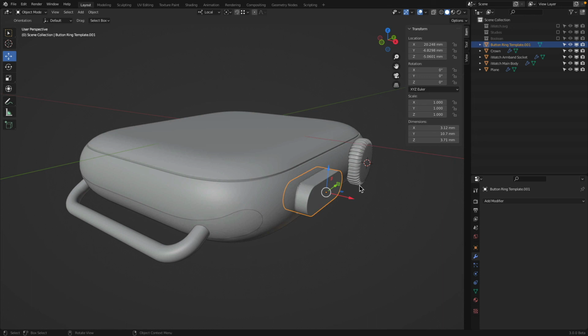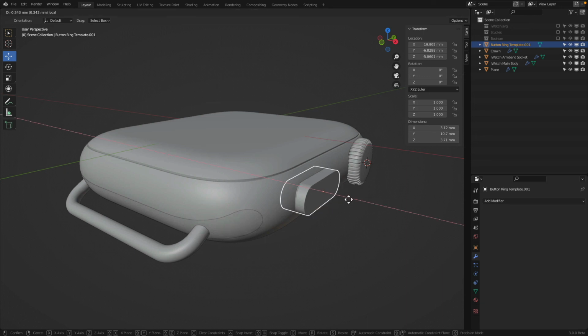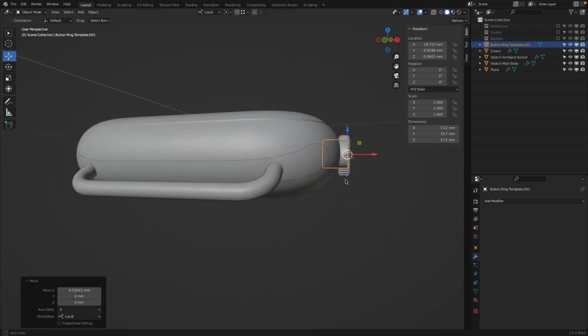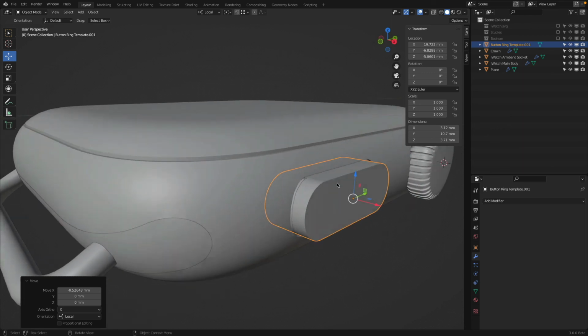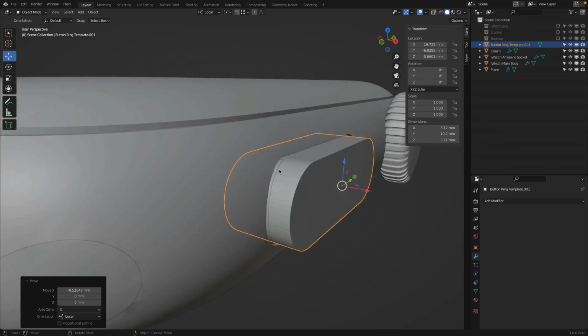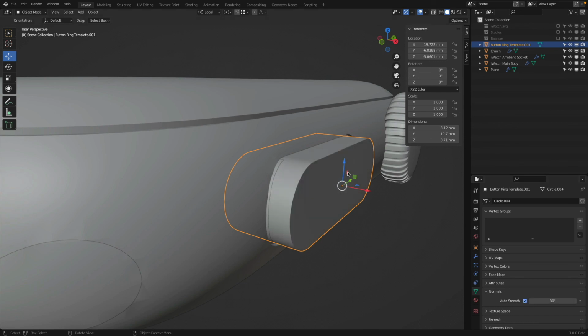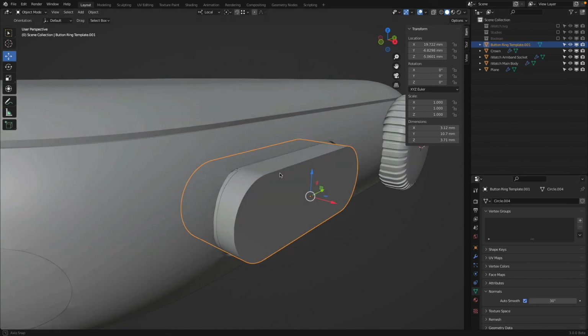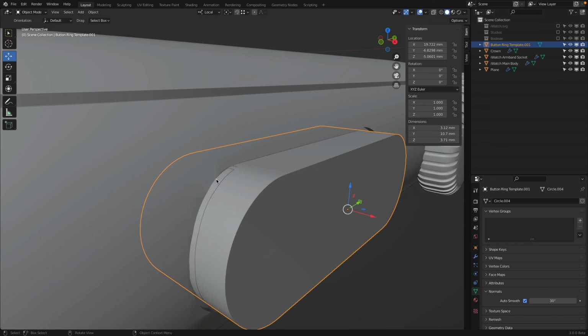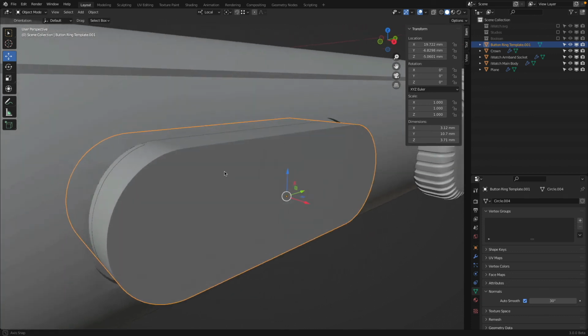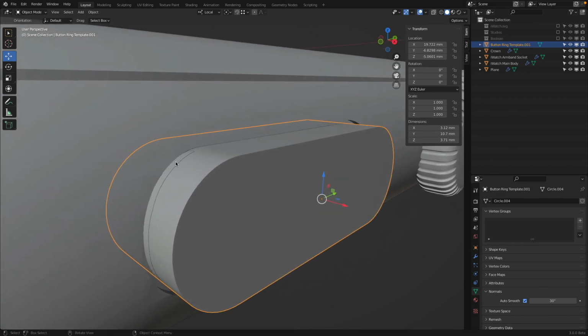So now I would like to be able to, well, we need to trim that button. How do we get that button trimmed? First, right click, shade smooth and auto smooth, so we have this edge cut. And then we can see here, this is actually the same. It needs to be a tick bigger. Okay, so now I can show you how we can do an offset surface.